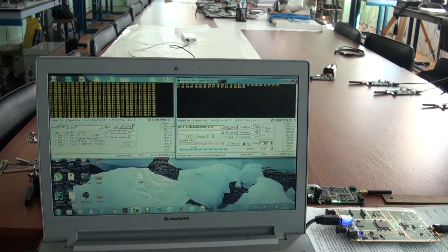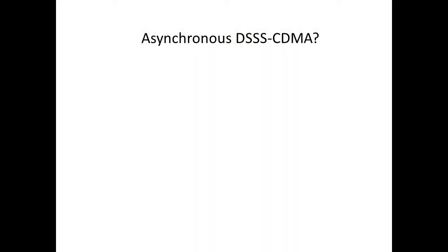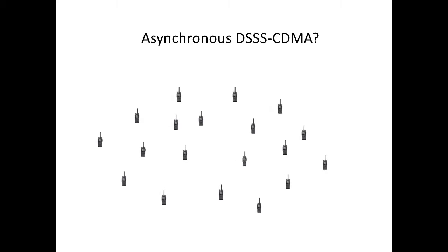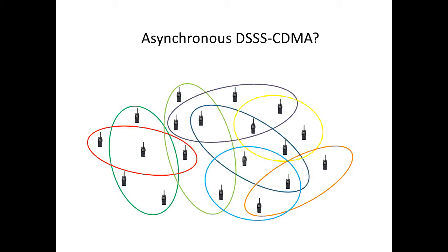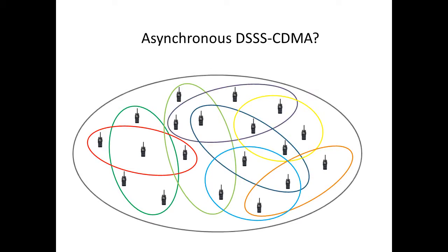As previously, receiving is successful, so this is like frequency changing, but really the same frequencies are used. And 8 links is not a limit for this configuration. So, what have we got in total? Usage of the given technology enables running several independent DSSS CDMA networks, or links, that are powered by different physical layer encryption keys in one limited area and on the same frequency without additional arrangements.